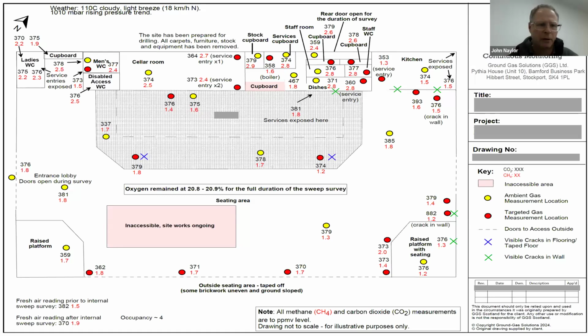We've recorded the weather. We've done some fresh air tests before and after to show that the equipment is responding as we expect. Would we just do one of these, or would we do a series of these tests? Because guess what? Ground gases react to a lot of changes in environmental parameters, such as pressure, or, particularly in housing, temperature might be a driver, which we see quite keenly with radon, for instance.